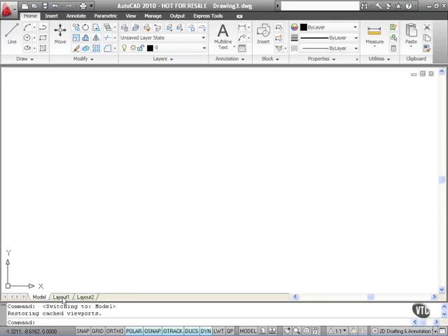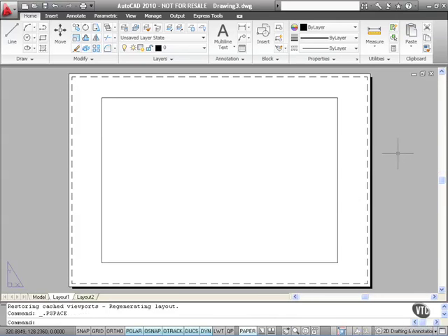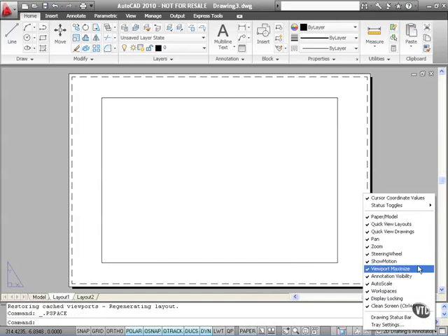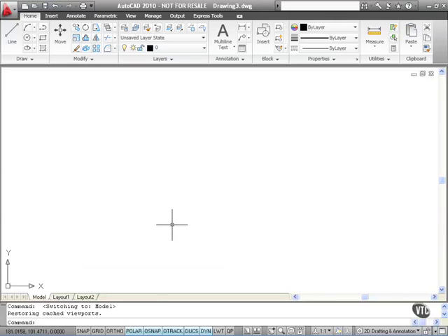If I go to a layout, like that, you'll see it's currently in model. If I double click outside the viewport and deactivate, it goes to paper. So it's the model paper toggle. I'm going to click on the little fly out here again and switch that off again, purely for spacing along the status bar so that I can read everything. Now let's go back to the model tab again here, so that we're not working in any layout tabs or paper space.